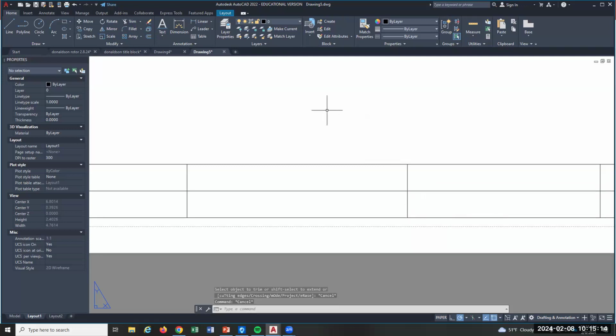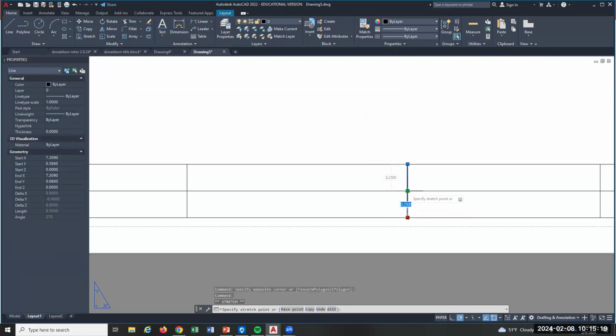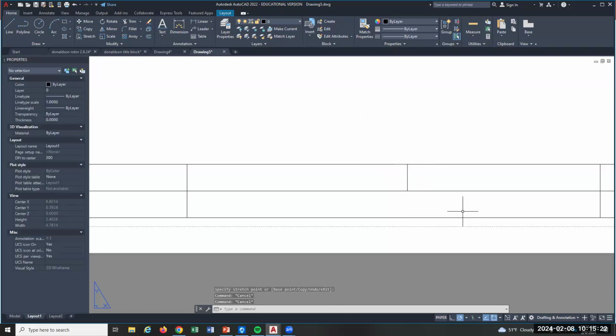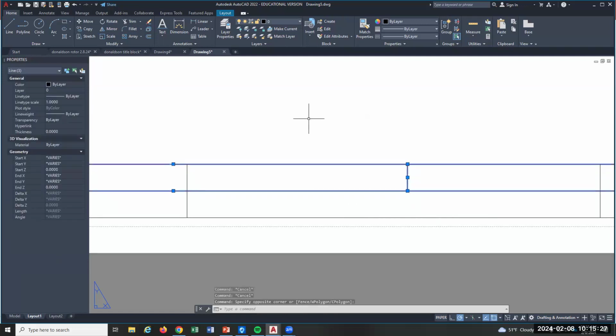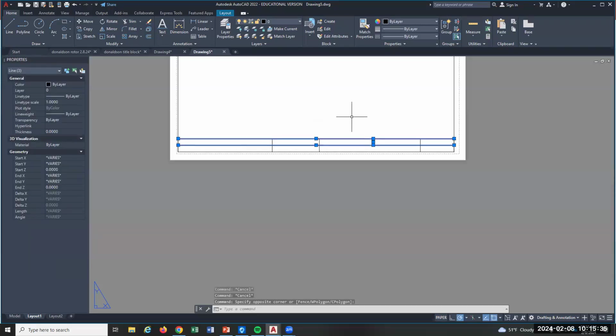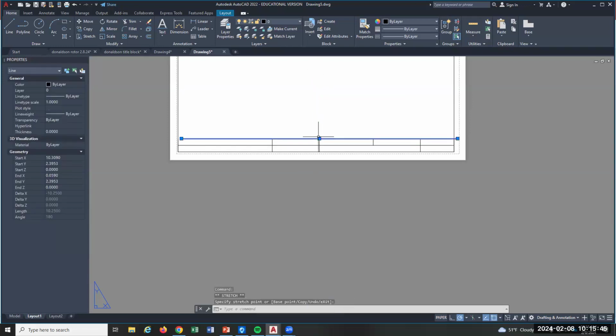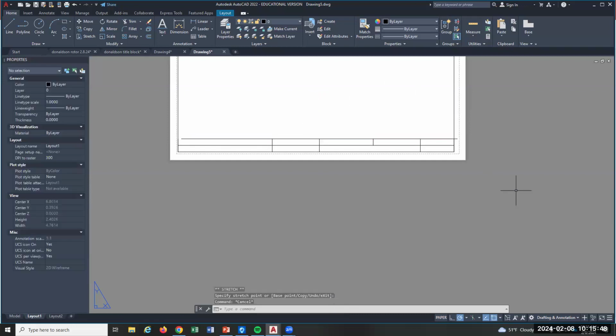And the other way is when you're not in a command, you can grip and then just grab a grip point and drag it up. So that's like the no command way. You can do a lot with grips. These are grips. When you choose something not in a command, that comes up, right? These are grip points. So lines have 3 grip points. If you grab the middle grip point, you're actually doing a move. So these are pretty handy. It doesn't look like it worked well for that because it slid it over. So placing it wasn't so great.